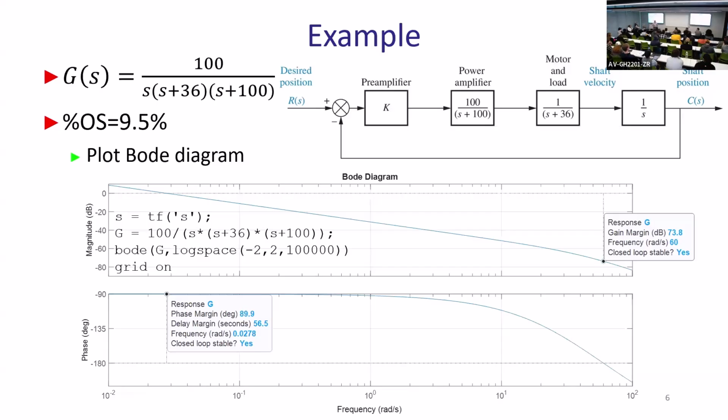Maybe you don't want the system to settle that quickly, like you actually want it to take some time. Correct, but opposite from what you said. Oh, okay. So what happens is that system will be extremely slow. Your settling time will be horrible. Yes, your overshoot will be zero. It will slowly, exponentially go forever.